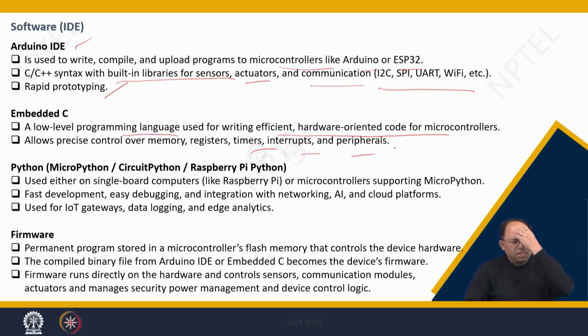Now, interrupts are something where the microcontroller waits for some change, right? So as soon as the change happens, it wakes up or triggers certain kinds of activities. So that's an interrupt. For example, if I have a microcontroller using an interrupt to detect that a particular vehicle has moved, the accelerometer will record some changes, and that will raise that interrupt request to the microcontroller to do some process.